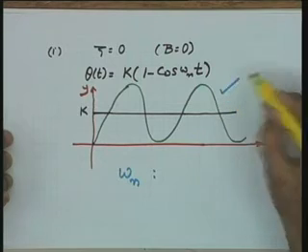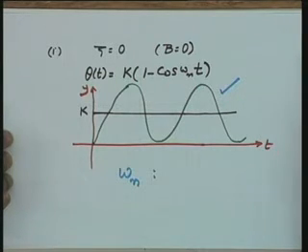Can you recall an example in which I made a mention that this type of oscillating behavior may be acceptable? If you recall, that is the example of residential heating. With the on off control system in that residential heating system, you see the output of the system was oscillating within a certain temperature band. So, the acceptance of this oscillating behavior is dependent on your requirement of the system, but in most industrial situations, such a behavior is not acceptable. Okay?